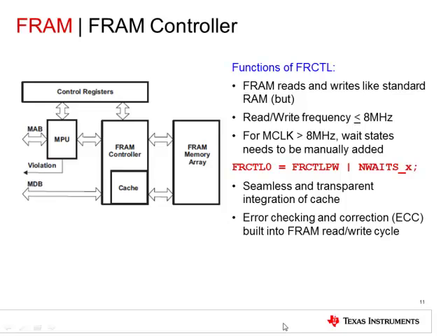There are 3 options for programming an MSP430 FRAM device. 1 is programming via JTAG or the SpyBiWire interface. 2 is programming via the ROM BSL, and 3 is in-system programming. In the next section, we will discuss methods to secure the device when using these methods to program the MSP430.